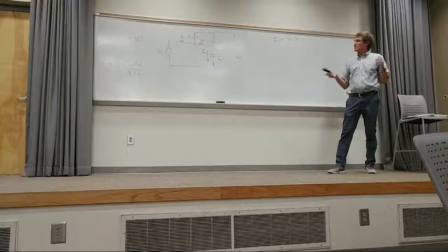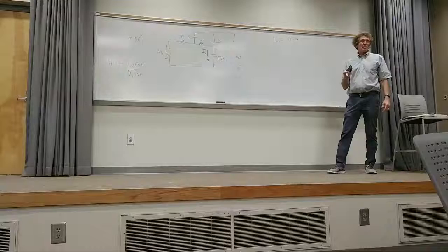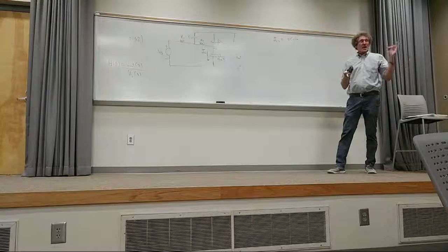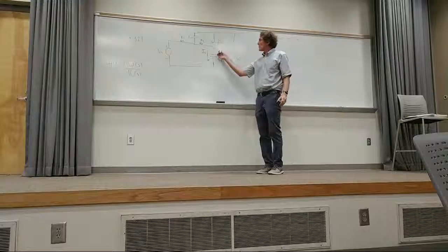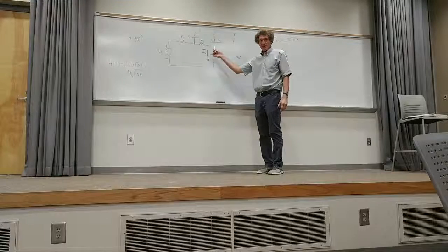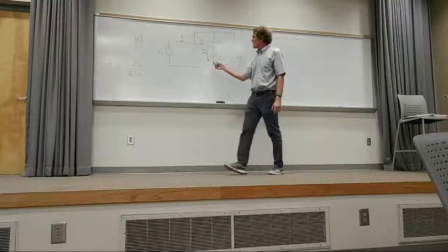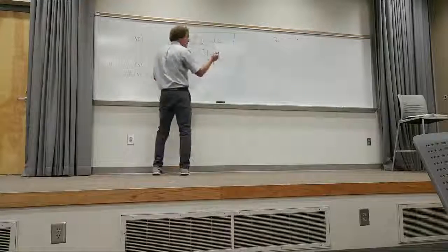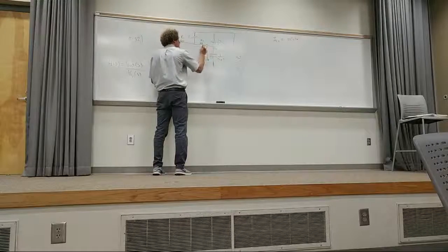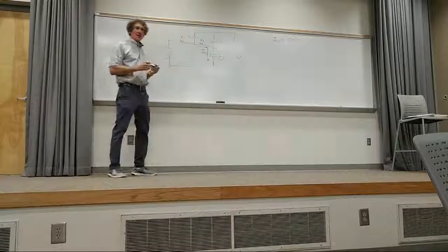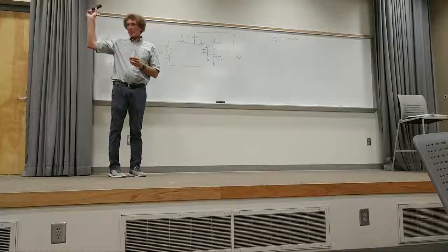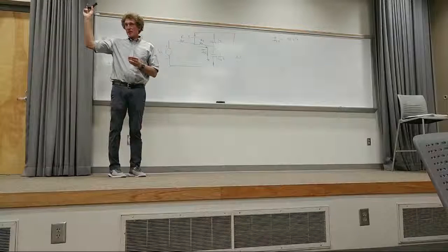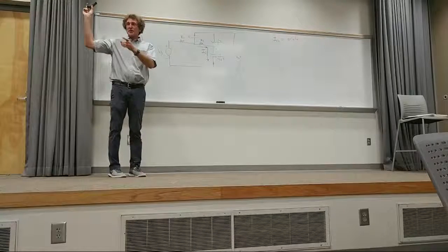How much of IC2 comes out of the positive terminal of the op-amp? 0. None. Please make sure you state that over and over. There's no current that flows out of that positive terminal. Understand? Because current is flowing, where must it come from? R2. It has to flow through here, right? So this whole thing is going to be IC2. Correct, class? Do you all see that? Give me a show of hands if you do. With me? What don't you see?